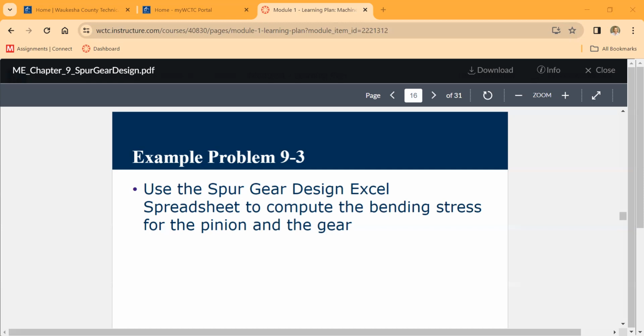It says the gear unit is enclosed and is made to commercial standards. Gears are straddle mounted between bearings, and the following gear data applies. The number of teeth on our pinion is 20. The number of teeth on our gear is 70. And our AV number, which is going to come again a little bit later, is called a quality number. It's going to be 10. Don't worry about clicking here, people, we're going to go through it. And then over on the side here, I have the gear RPM at 500.